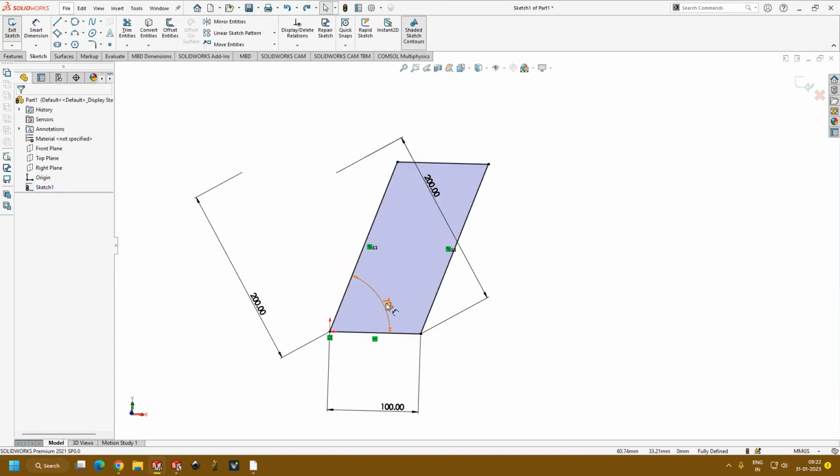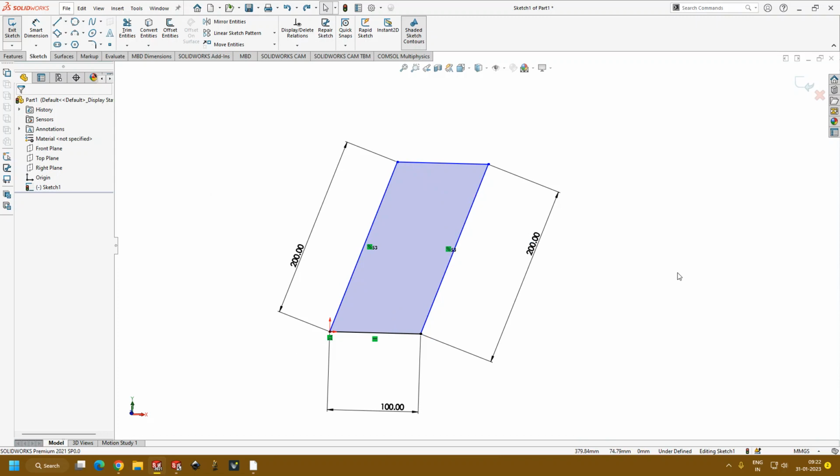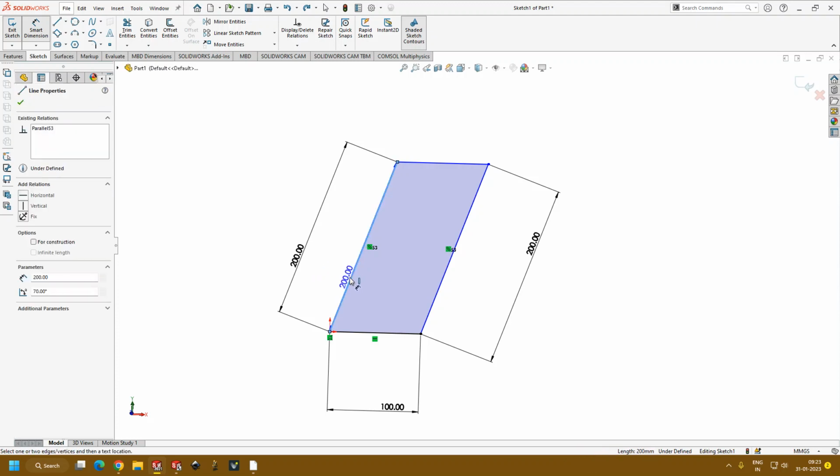Okay. So let's say I'm deleting it again, okay, till here it's fine. And then click on smart dimension. Okay, underneath the arrow, you will see the symbol called smart dimension, below the arrow, right? So then it is very simple. Once you come to this line, the line changes to orange color. Okay, you can see this difference. When you go on the line, it will be in orange color. Select this. Once you select, it is again blue color. Okay, with just one click, you will see this kind of thing if you move the cursor.